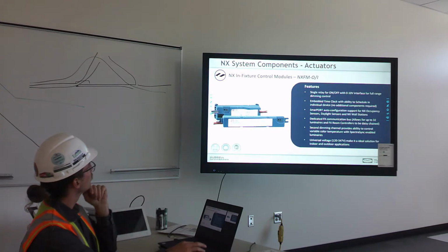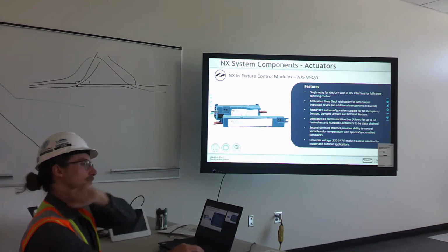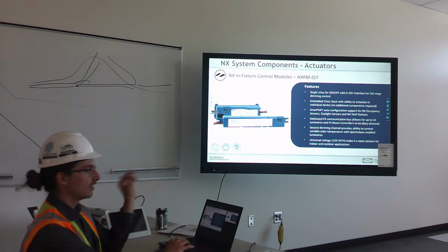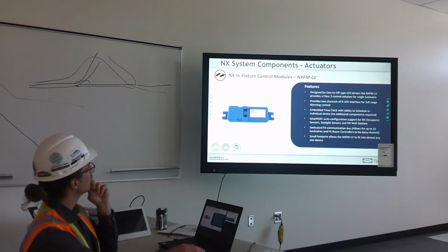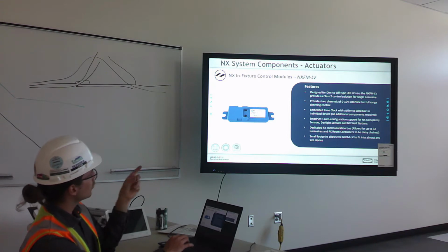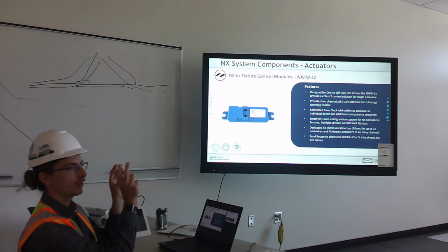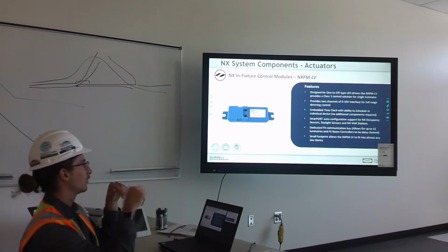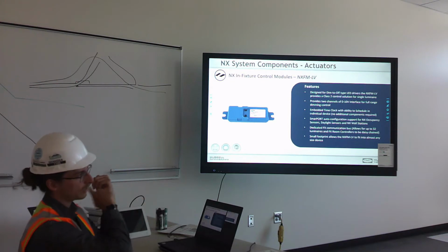Let's see. In fixture modules, the only place you're going to find these is in the parking lot poles, which are smart fixtures. They just have a dimming output that dims the light all the way down to off, and it's actually going to look like this, our low voltage fixture module. So that's going to be connected to the sensor that's in the fixture. You've got a motion and photocell and Bluetooth sensor all in one. And then that's also going to be connected to a radio module that allows all the fixtures to talk to each other and then back to the area controller.